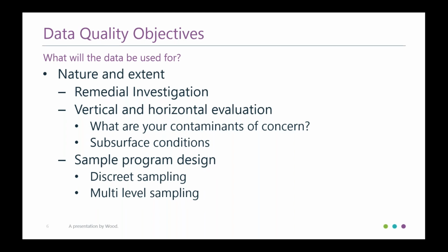You're going to start looking at what your geology is. Do you have clays? Do you have aquitards? Is this sand that's going to go straight down to the bedrock? So those types of investigations might need entirely different wells than you'd use for just a site characterization. Your sample program design is going to get to more discrete sampling. You're going to be focusing in on fractures if you're in bedrock, or geologic units that are more transmissive. And you're probably going to be looking for multi-level sampling. Vertically, where is it?